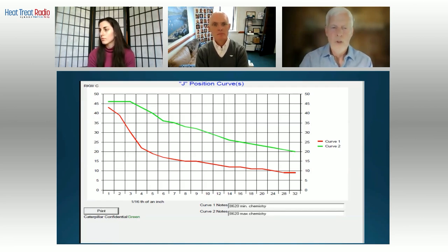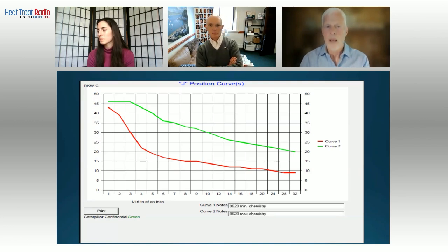So what I've done here is, if you recall, the J3 on the 4320 material that we looked at, the hardenability guaranteed, had a 10-point range. If you look at this particular heat, this is what we call the open chemistry. So this would not be a hardenability guaranteed material. So what you have is the upper limit is higher than what you would see on a hardenability guaranteed material, and the lower limit is lower than what you would see. So the variation in a quote unquote standard SAE J403 8620 is going to be much wider.